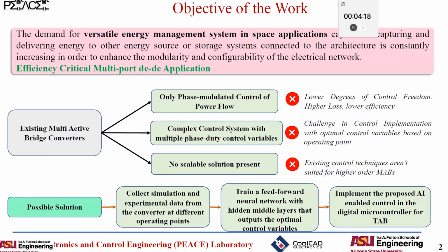With the emerging power and energy needs in the ongoing and upcoming space missions, the demand for multi-port power conversion systems to meet different types of energy management needs is omnipresent, as you know. Moreover, the next generation power conversion systems are expected to address the integration of various energy storage and source ports in a single integrated, efficient, reliable, and high density manner to make the space missions more sustainable and cost effective. In this context, this particular problem can be solved by using multiple dual active bridge converters placed between the respective source and the load ports.